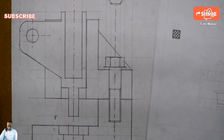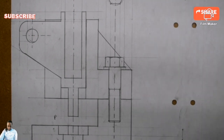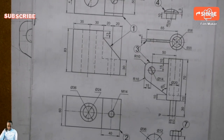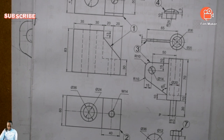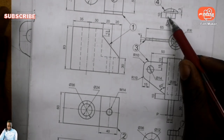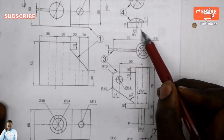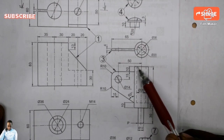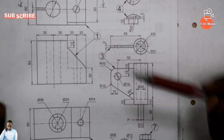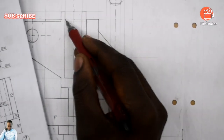So item 4 is the cap. You must know the function of the cap if you've done your trade N2, fitting and machining N2. So now let's fit item 4, which is the last one. Item 4, the outside diameter is going to be diameter 20, which corresponds with this one there by item 3. Item 4 has to be fitted into item 3. You understand? So it's already there.